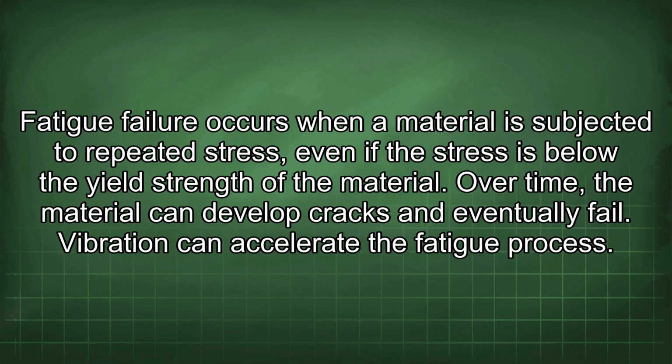When troubleshooting a vibrating busbar system, it is also important to consider the possibility of fatigue failure. Fatigue failure occurs when a material is subjected to repeated stress, even if the stress is below the yield strength of the material. Over time, the material can develop cracks and eventually fail. Vibration can accelerate the fatigue process.